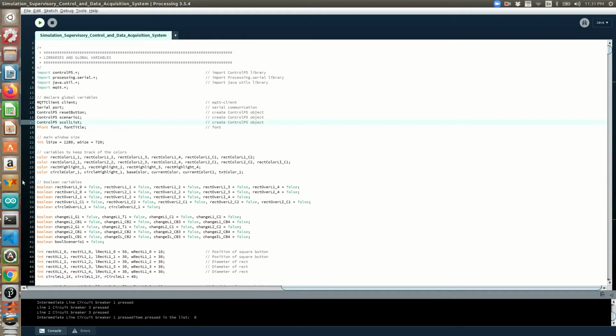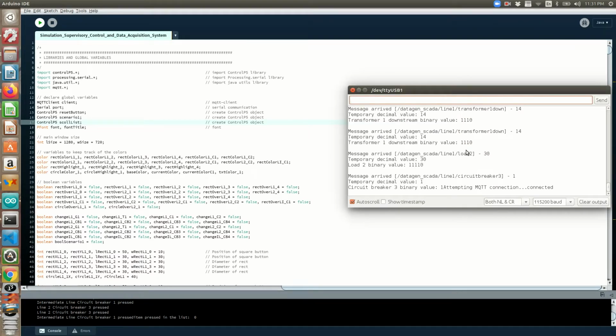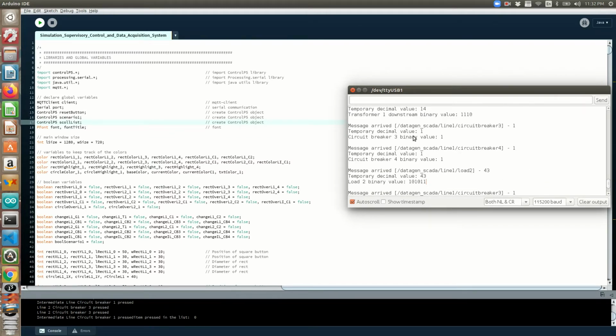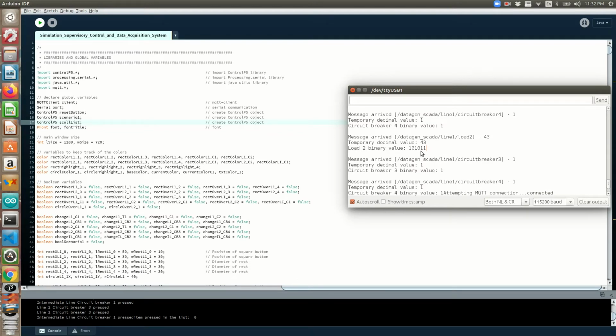So next I will just try to monitor using some debugging LEDs the behavior of the loads. We saw here that the loads, which has a random value, changes all the time. So because these values here are converted in binaries, I just went and connected some LEDs to the pins associated to each of the values, and we can see how the LEDs are turning on and off depending on the value that they receive. So this was a way I was able to debug the digital outputs at the hardware level. Because I didn't have a multimeter or an oscilloscope, I couldn't check the digital to analog conversion, check the voltages that I was getting at the end of the DAC conversion, and also check the analog output directly of the ESP.